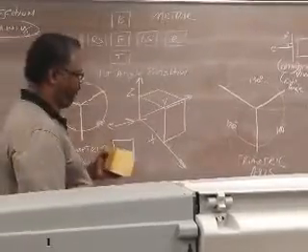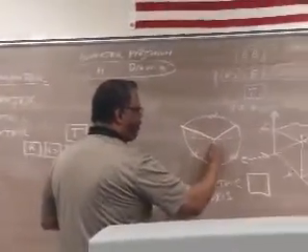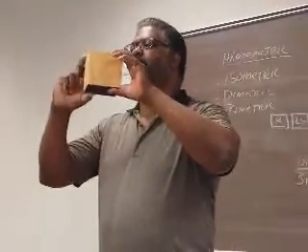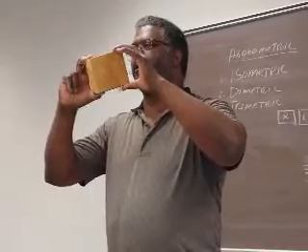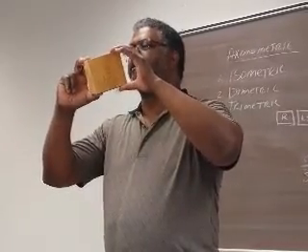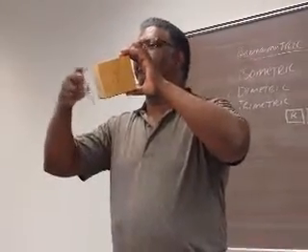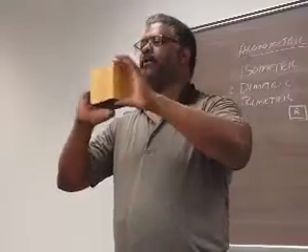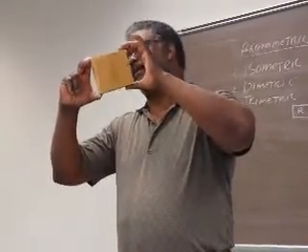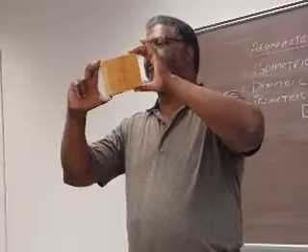So we would get an orthographic view. But if we rotate this object so that a corner is facing us, then we pick up this edge. And then if we rotate it along the next axis here, it can be rotated at any angle, but for the specific angle you do a 45 and a 35 degrees, 16 minutes, something like that.